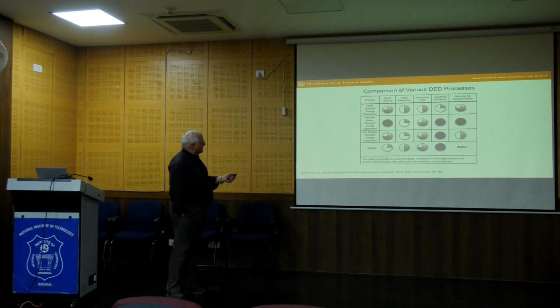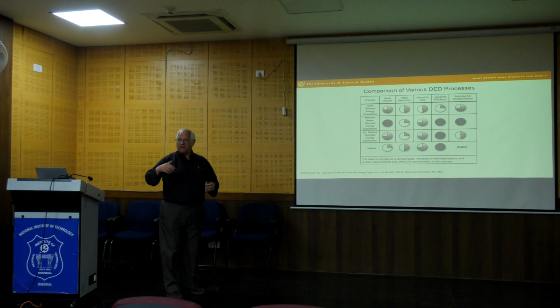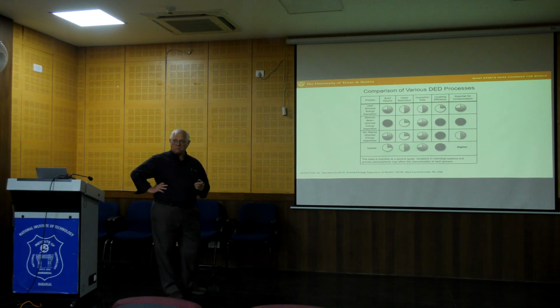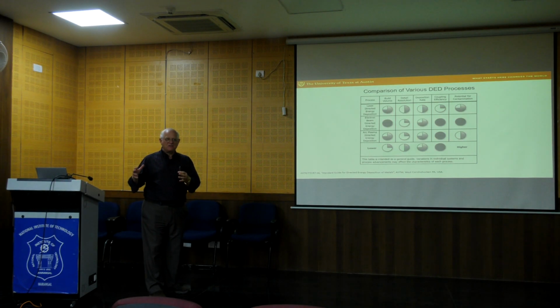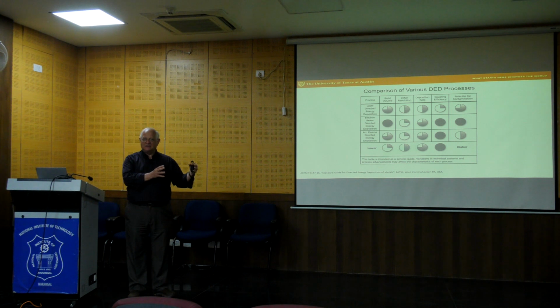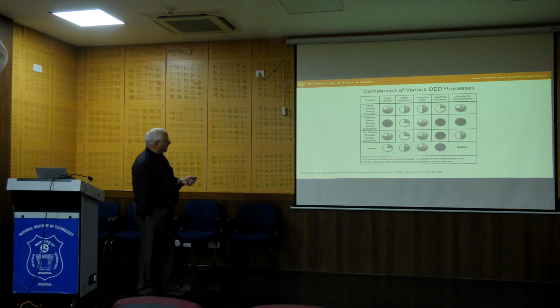Moving on, though, for build volume, the electron beam, the Sciaky type processes, is really where the electron beam shines, and with the coupling efficiency, because the electron beam couples very well with metals. It's also very good on deposition rate, as good as we can get in depositing materials. But it suffers on detail, right? With these processes, and this is true for really all of manufacturing, if I want to dump a lot of material quickly, I usually suffer on the detail and the resolution. That's true for almost any process, certainly for additive.